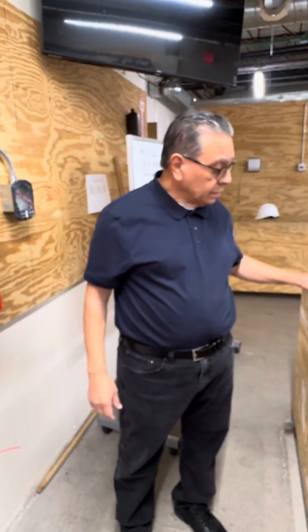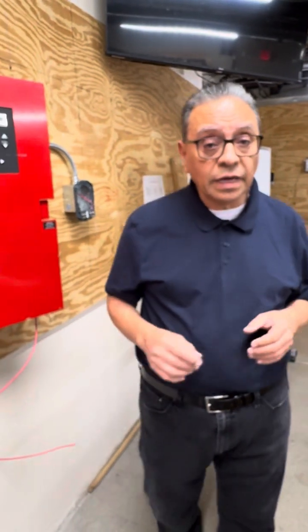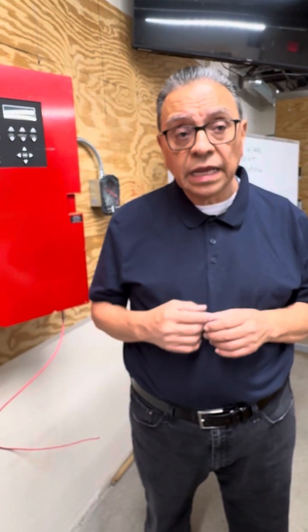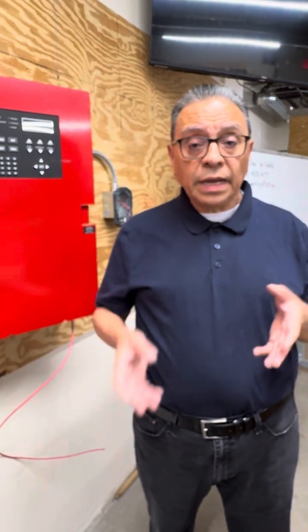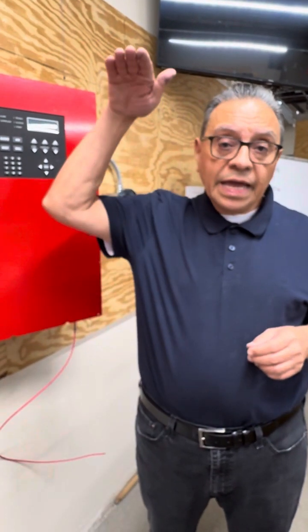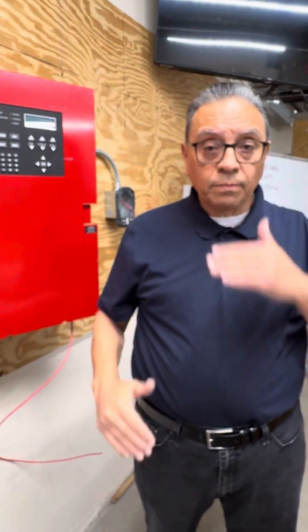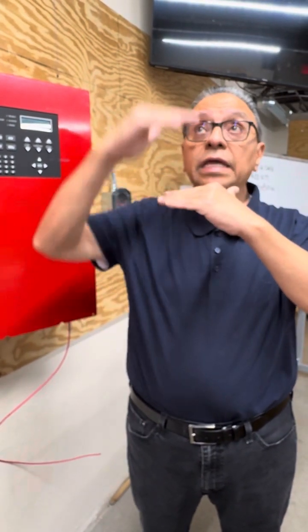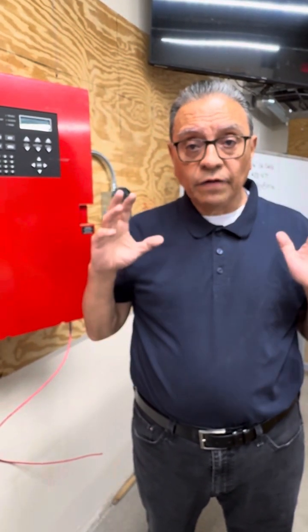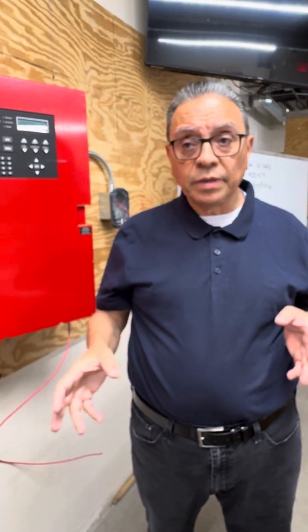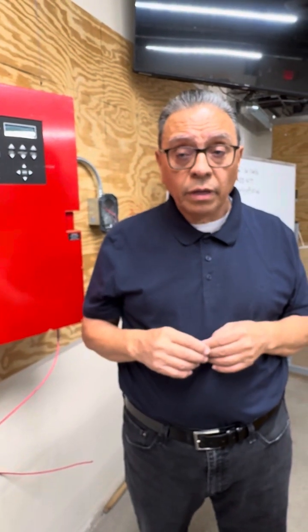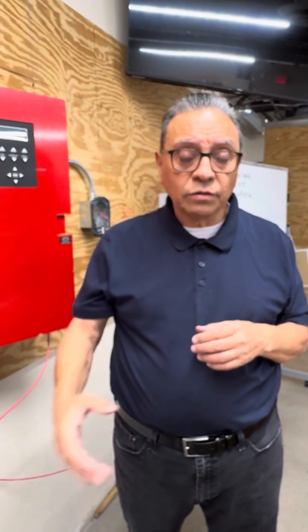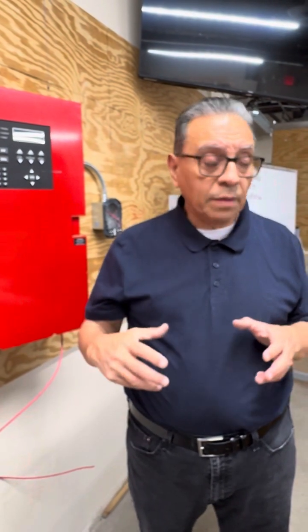It has to be gauge 18, properly classified to be used in fire alarm systems, and plenum classified, plenum category. Plenum category means that I can run it in the plenum. The plenum is the space between the ceiling and the roof. If any incident happens, such as a fire, this kind of cable will retard the propagation of the fire, and the smoke emitted by the plastic sheath is not toxic.